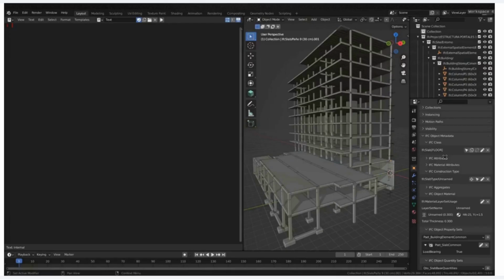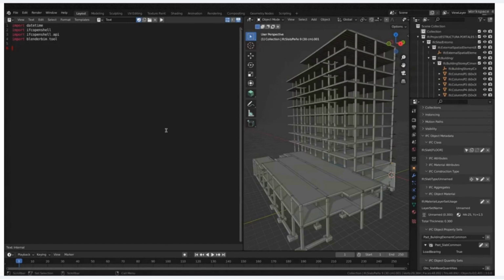Now, BIM isn't just about architectural design and engineering services. It also includes construction. You'll find information about material sustainability, cost schedules, and information about all the resources used during construction. Now let's pretend that we're going to create a construction schedule. Then let's get the BIM model that we've already loaded into our session. The first thing we're going to do is add a new work schedule. Let's call it construction. Our schedule will have a whole bunch of tasks in it.